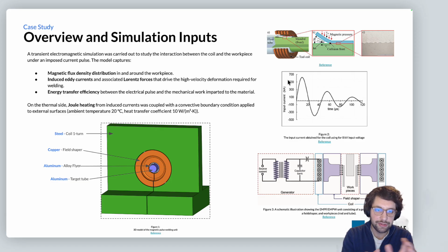Sounds great. Now, just to reiterate what we're trying to get out of this simulation in relation to both the tooling, alignment, and misalignment, by investigating the air gap between the copper field shaper and the aluminum tube, but also we want to vary the conductivity of our aluminum tube to investigate realistic scenarios of what happens when I'm working with different suppliers and I'm having this grade and that grade, and I need to make sure that my machine is working efficiently for a wide variety of aspects.